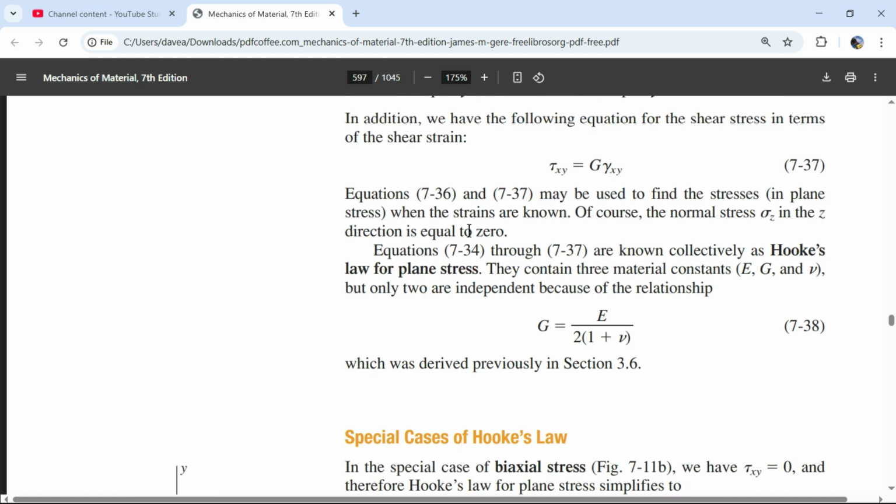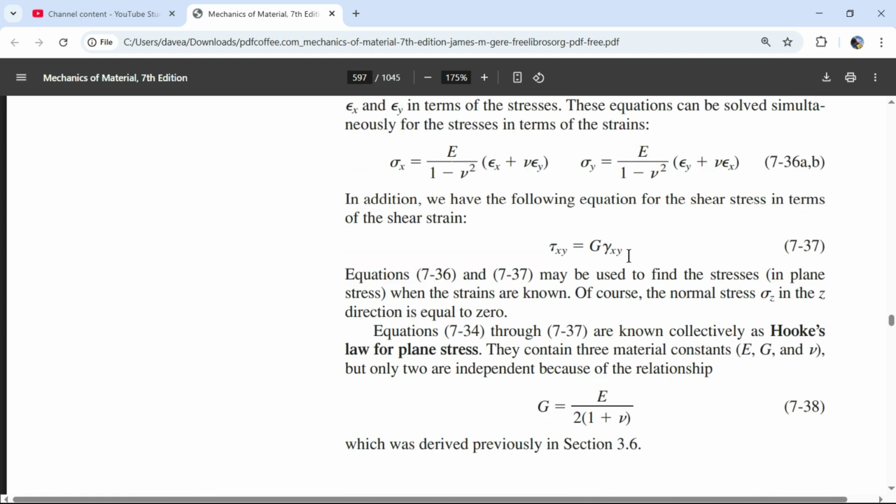Yeah, so this is the equation. I mean, this is the way to do it, because this is y is equal to mx plus b. Except when this is 0, this angle is 0. You know what I mean? So your equation goes through the origin. And as a linear equation, y is equal to mx plus b, your y-intercept term b is 0. And so this value for shear modulus of elasticity is your constant that is the slope of that line.